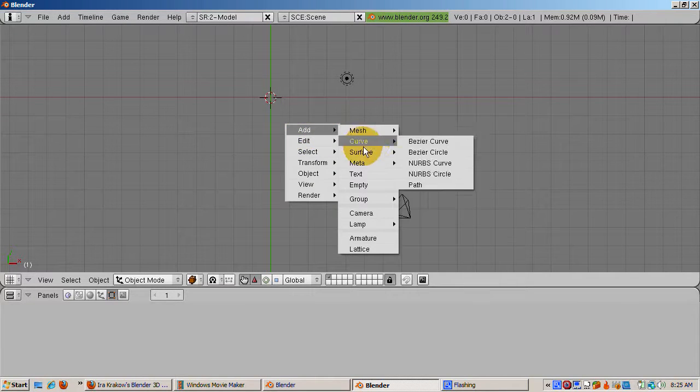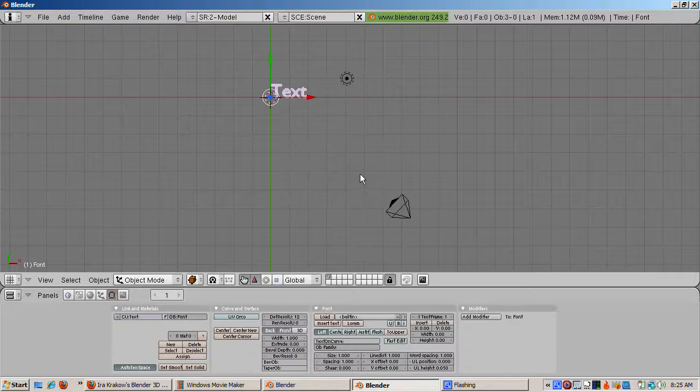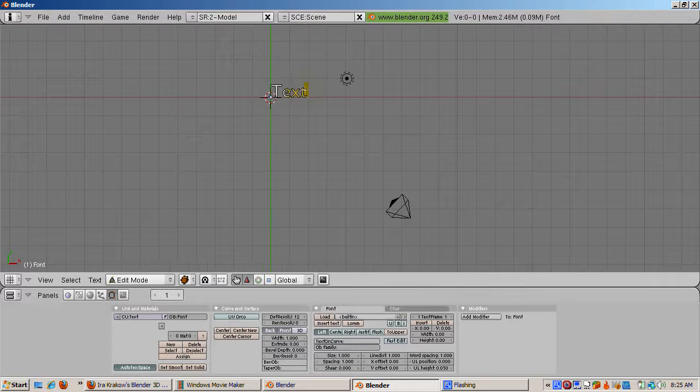The text object has the word text placed on the floor. The text object is actually a curve object. Press Tab to go into edit mode. For a text object, when you press the Tab key, you can change the text. There is a cursor, a vertical bar. Let's change the text so that it says Blender 3D text is so very cool on 3 lines.